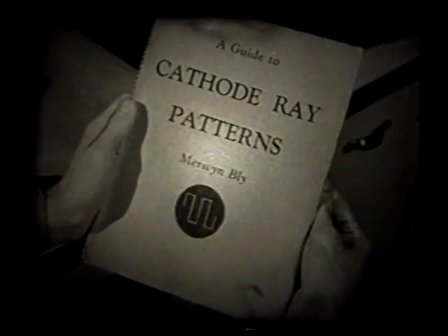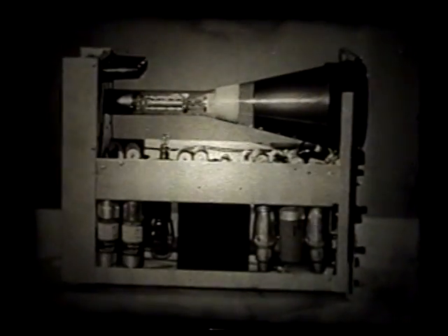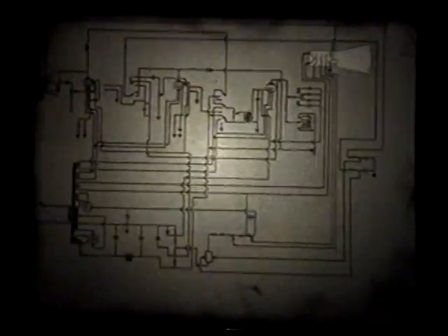By measurement and comparison of these graphs or waveforms, a number of complicated electrical tests are made more simple and more accurate. There are different types and models of cathode ray tube oscilloscopes. All are fundamentally the same. The oscilloscope consists of a number of component parts and their associated electrical circuits. Let's see what they are. The vertical amplifier, the horizontal amplifier, the sweep generator, the power supplies, the cathode ray tube.